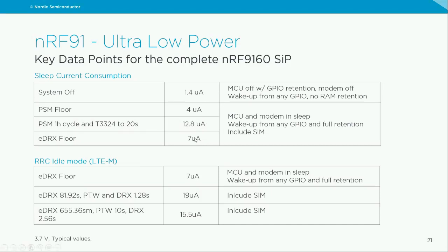And in these sleep modes, another thing to remember is that the modem and the application are fully retained. So you don't have any huge boot up power cost here in order to reconnect to the network or reinitialize your operating system and the application. They can basically boot up in microseconds and start running exactly from the same point from where you went to sleep, since all the stacks and all the memories are retained.